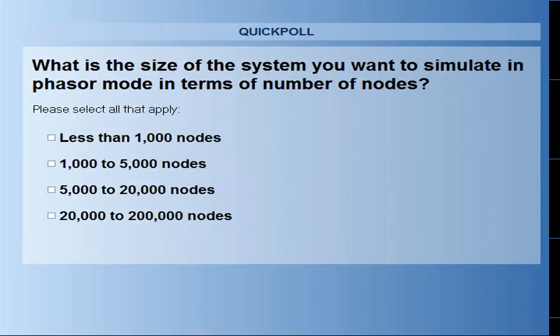In the next phase, when the Coachella Valley transformer tripped, the system gets stressed further. You can see the angle difference increase, as well as the current out of the zone. When the next event happens, it did some load shedding, but it didn't help much. You can see the current dropped a little bit, but it's still in a very high loading condition.